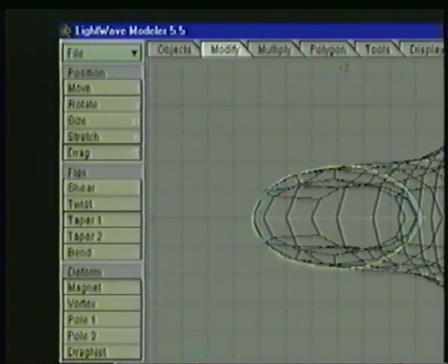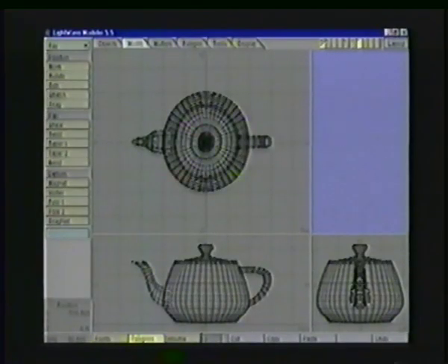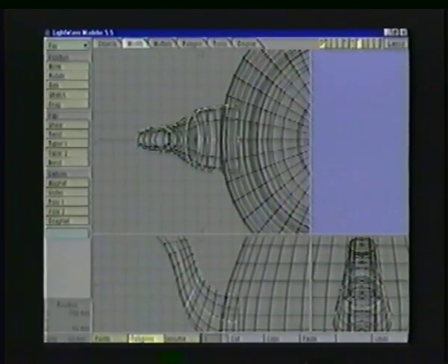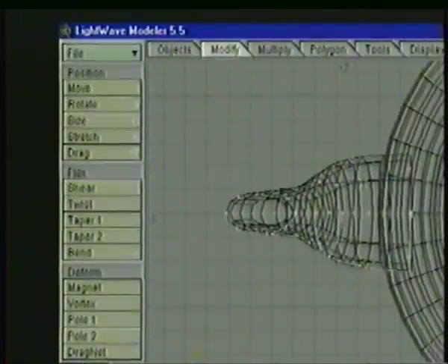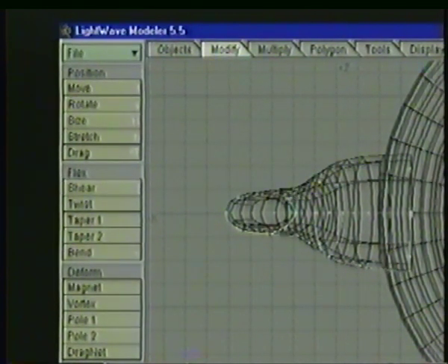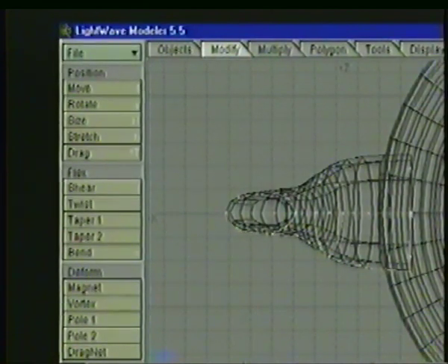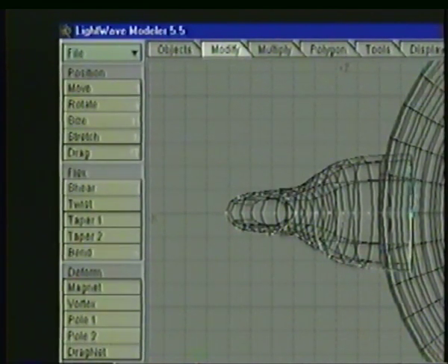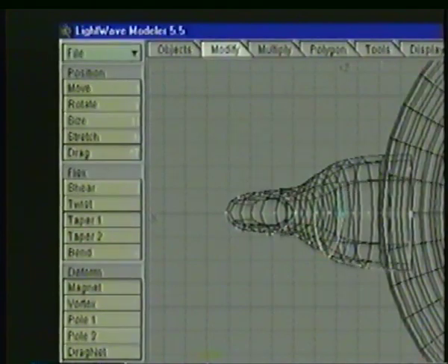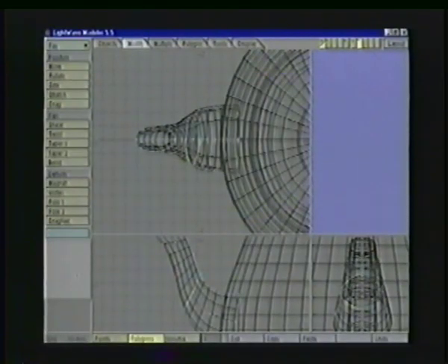Once I'm happy with all of these, I can then delete that whole entire half that I mirrored over. I'll select all the curves and just hit delete on the keyboard, and they're gone. Notice what stays behind. There's some stray points. Well, if we select these curves, you guessed it, they're now start and end CPs, which is the result of the smoothing process. Lightwave is smart enough to realize you want to keep those points so that you get a nice smooth curve, a continuous smooth curve across the center.